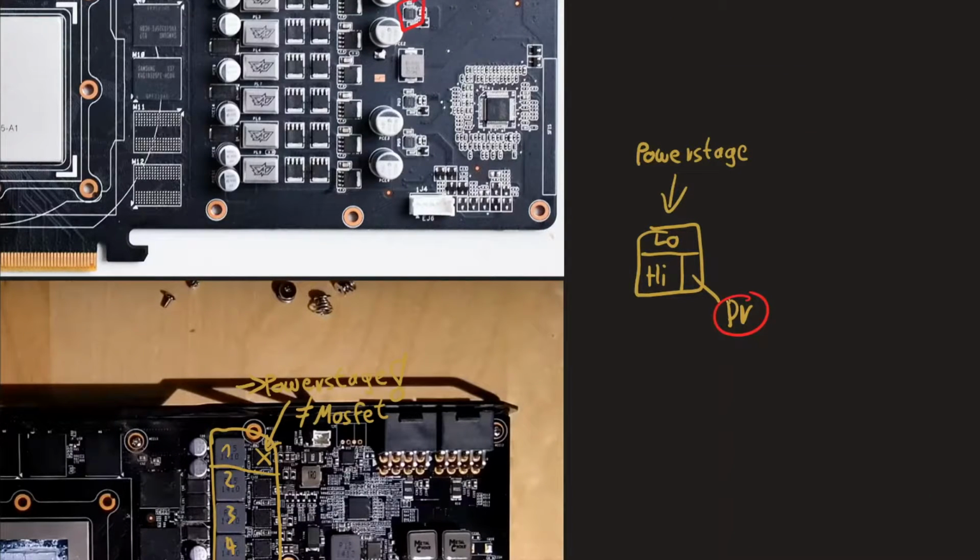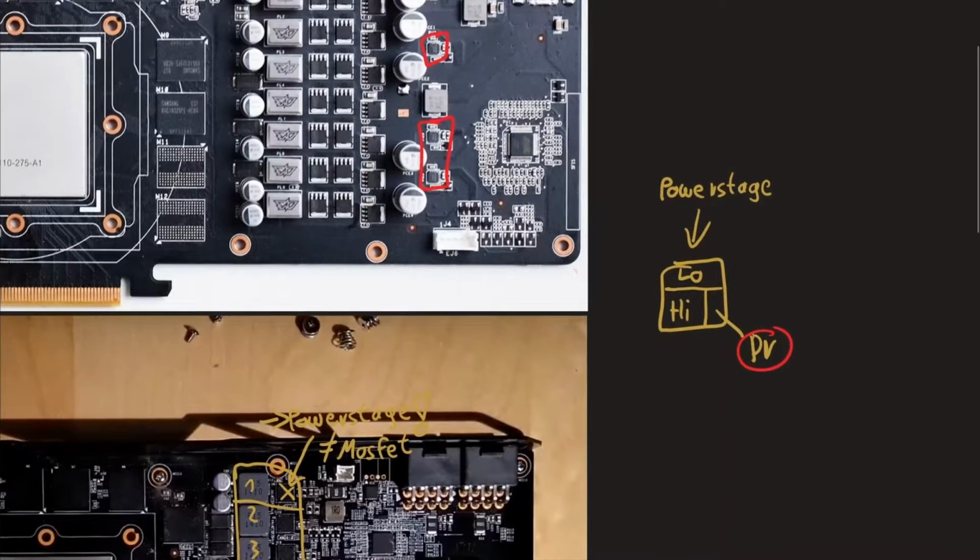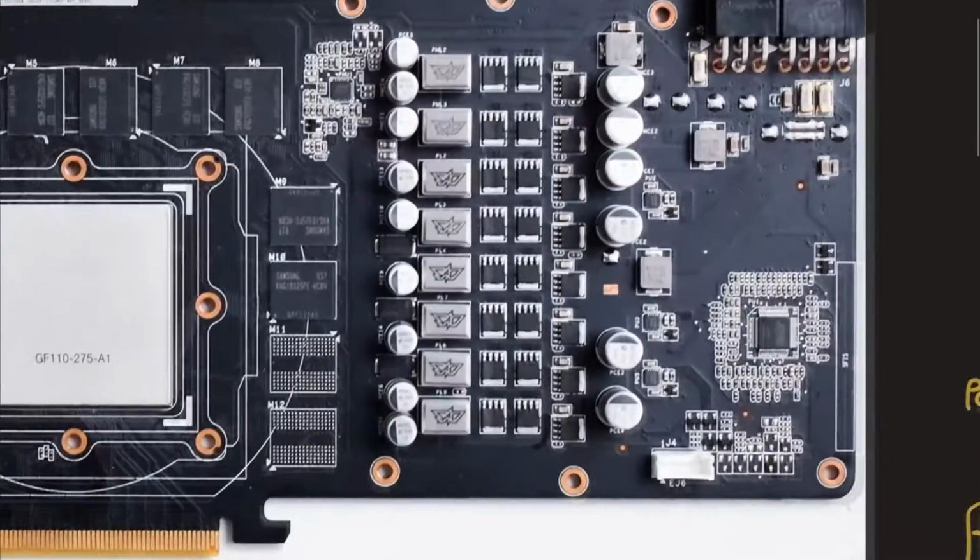These are just external drivers. Like the MOSFETs are discrete ones, so you also have discrete drivers. There are discrete MOSFETs that include drivers, but on that card you have discrete drivers. So it's just that thing put onto there. And those are also dual drivers, so they can drive two phases, which is why you only have 3 of those on there and not 6. Yeah, but back to doublers.